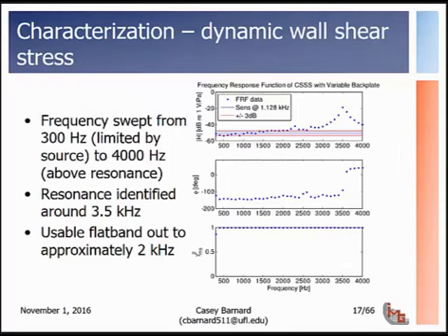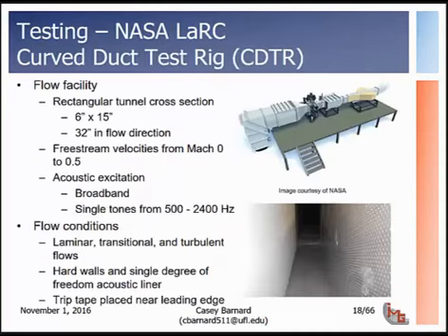We generate this by basically having a movable end wall that locates our sensor at that quarter wavelength node for various different frequencies. We perform the sensitivity test at all of them, and we can generate this nice plot up here. You see your resonance is roughly around 3.5 kilohertz, a little lower than we'd like. But our usable flat band, from the plus or minus 3 dB standard, extends out to about 2 kilohertz, right about here. And coherence is good, and phase, of course, is for transition, 3.5. So it's all well and good on the desktop.